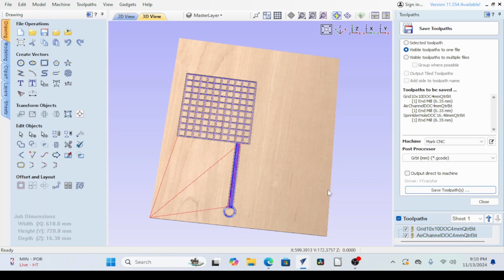I would recommend when you machine these, of course, because it's melamine, you don't want to breathe that dust, have a dust mask on, have, of course, safety glasses on. If you have a dust boot, I would highly recommend put your dust boot on when you machine this out. This length, remember, is going to be the length from your spoil board to the edge of your CNC bed plus 5 more inches, and that'll give you plenty of room to hook that vacuum up.